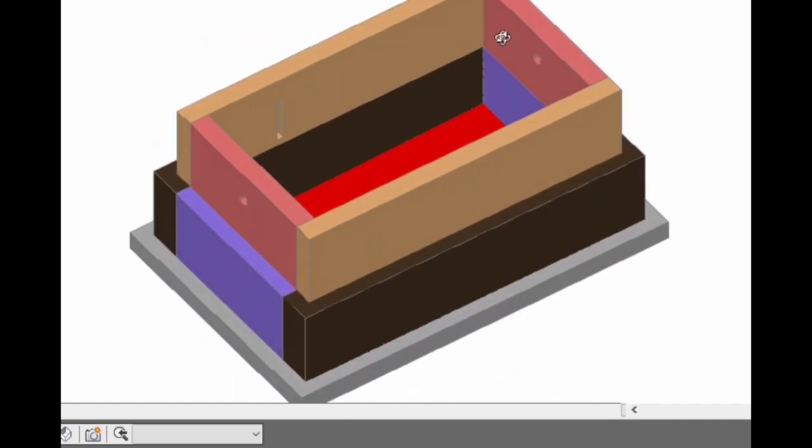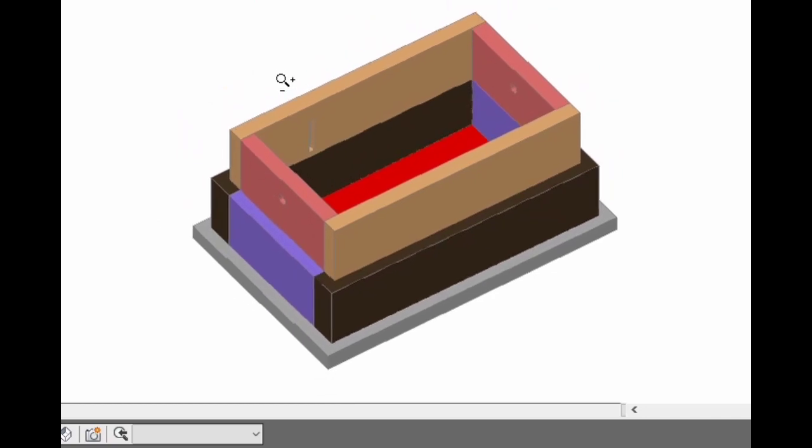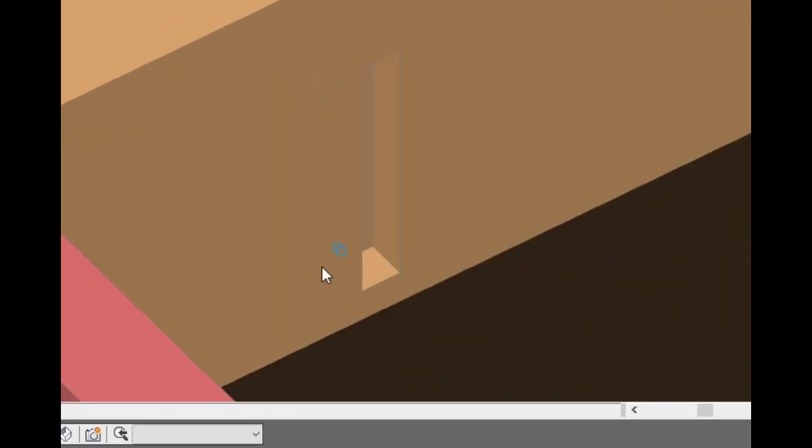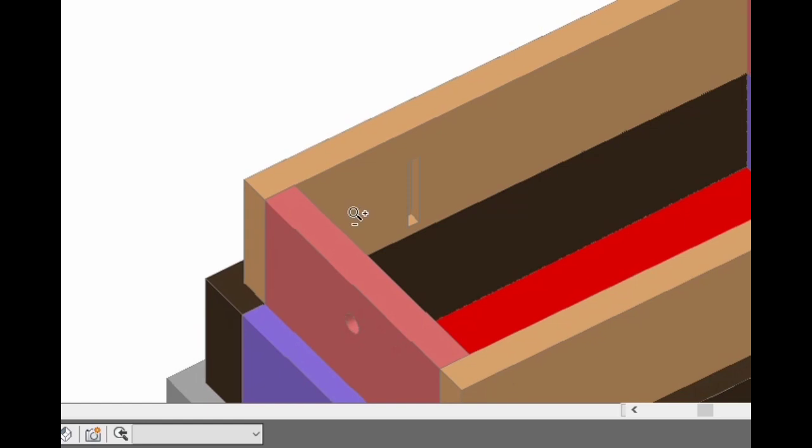You can see the concrete bed, the offset all round. This is the long wall, the short wall of the first step, the long wall of the second step, and the short wall of the second step. These are the things which is to be kept in mind while estimating the different quantities. So, kindly have a view of all these things. Remember the components that are placed. Now, you can place the baffle wall here, where there will be a sitting of around 5 to 10 centimeter. You can see the opening that has been made in the long wall here to keep the baffle wall in position.